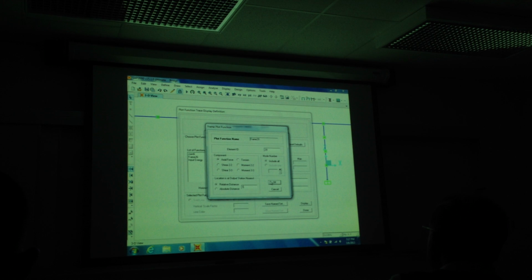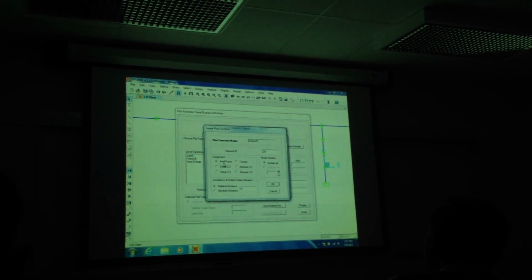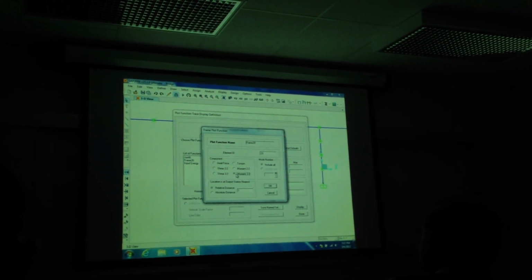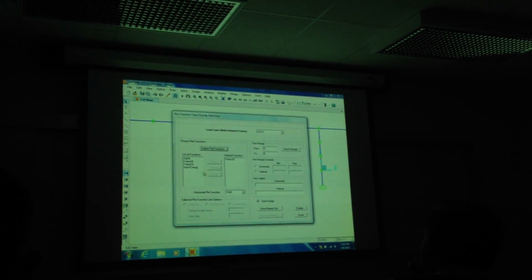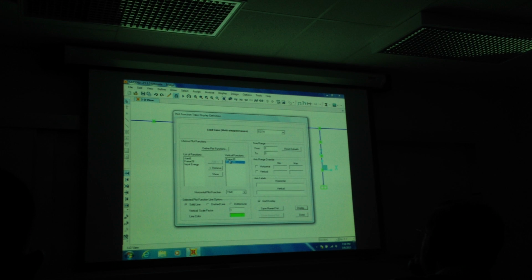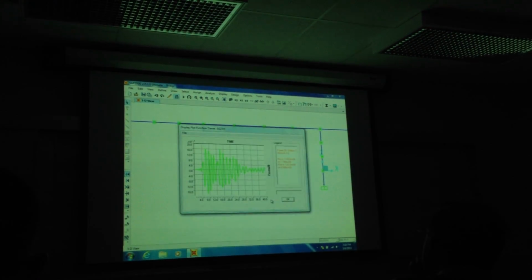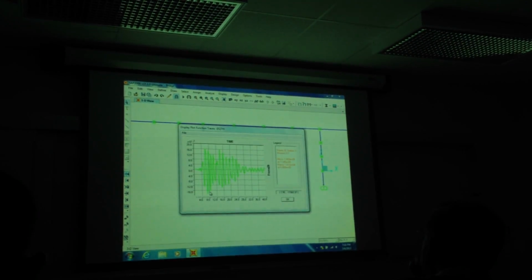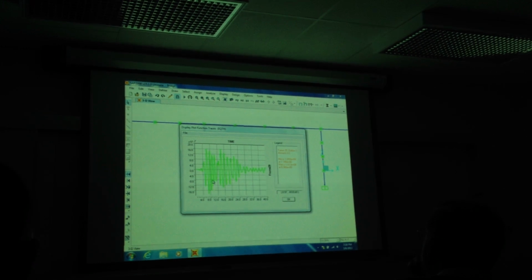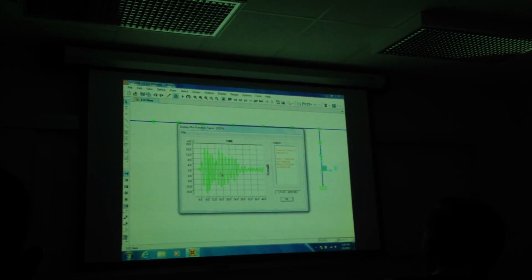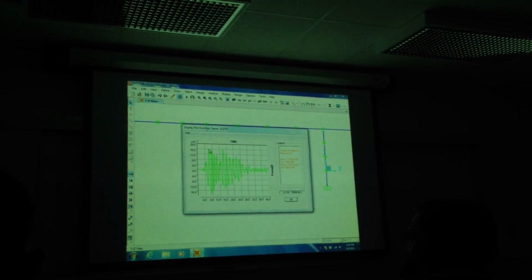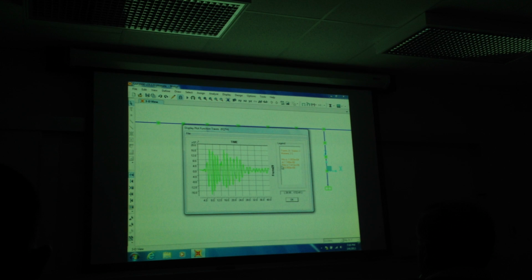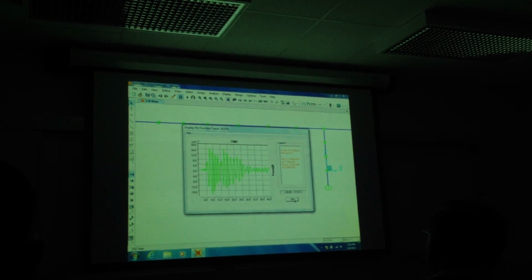Let's say OK. Oh, that'd be axial force though, right? I want Moment 3 to create. That's what I'm interested in. So say OK. So it's 29. Move this back. And you can see it's definitely smaller than the moment at the bottom. The moment at the bottom is a maximum of just over 20,000. Here we're seeing 18,000. So it's smaller, but not a lot smaller.